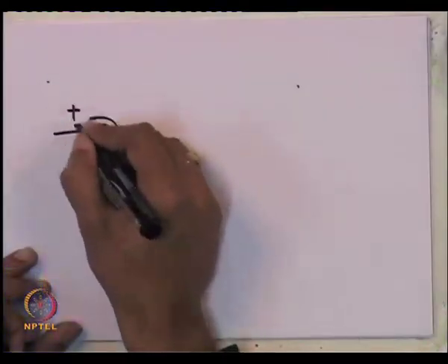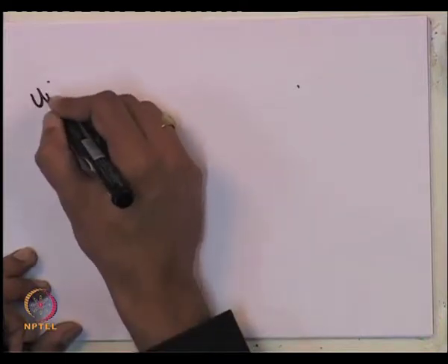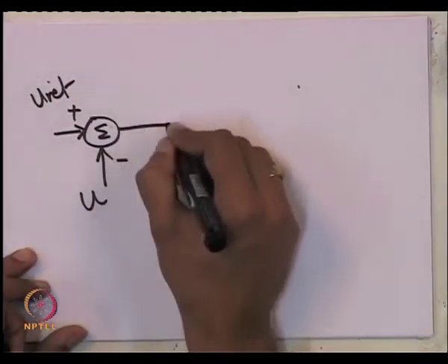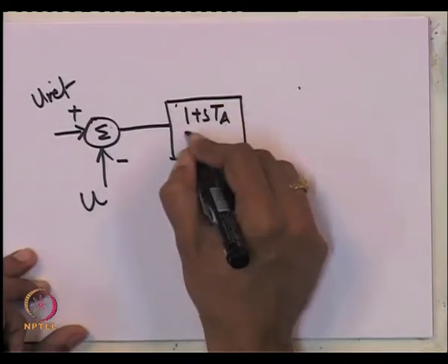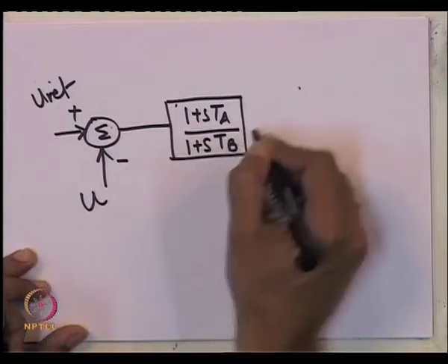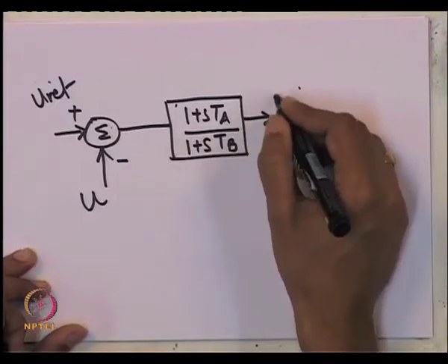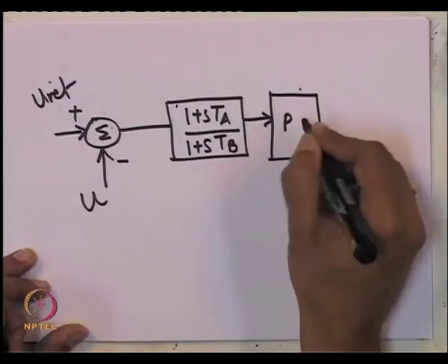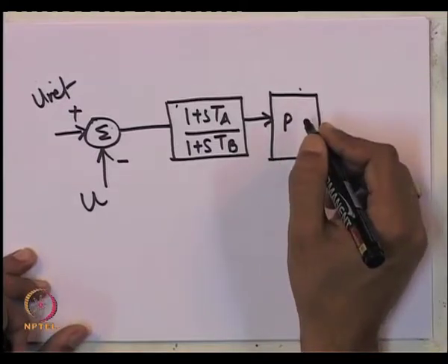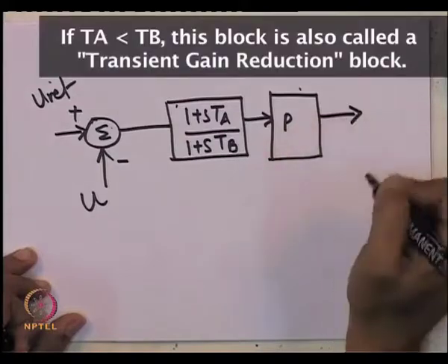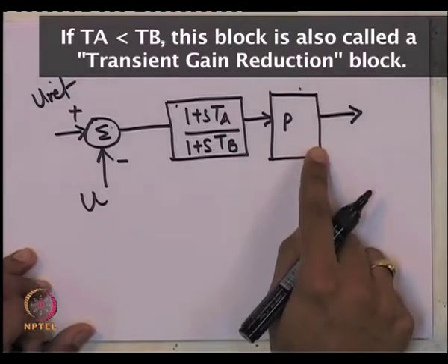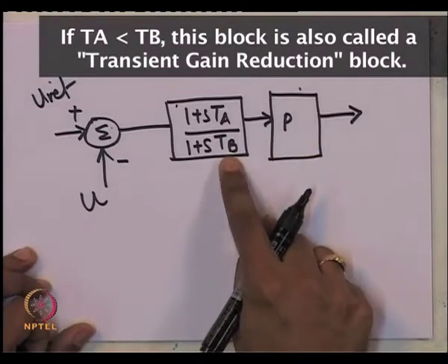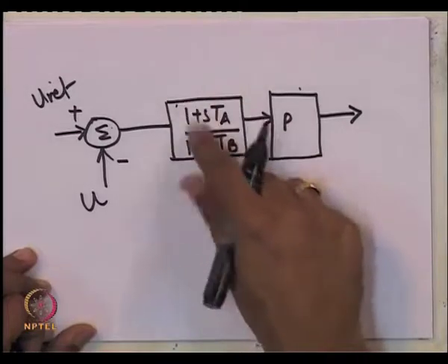For example, with a plain proportional integral controller, you may not get a stable performance. So, you may have to add a lead block or a lag block in order to improve the performance of the P or PI controller which you will use. So, this is one thing which you may see in a control system, that in addition to the proportional or proportional integral controller, you also have these blocks which try to improve the response.